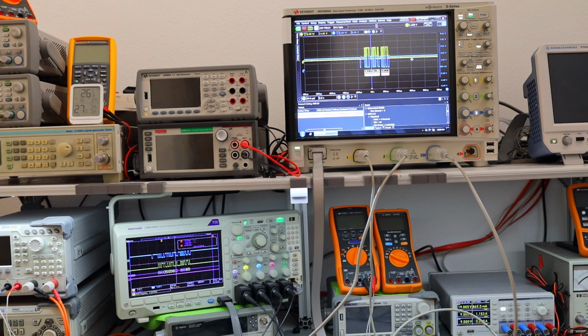Now we are going to cover one really high-speed bus. We are going to talk about USB, and we will try to decode every type of USB you can imagine. We are going to start with USB LS, which is low speed, 1.5 megabit per second. Then we will go to USB FS, which is 12 megabit per second. We'll go to USB HS, which is 480 megabit per second. And in the end, we will try to also decode USB 3.0 with 5 gigabit per second. So decoding USB 3.0 is going to be very, very interesting.